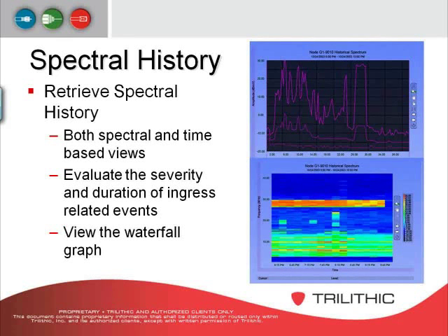And then on the very far right side, there are color codes that show amplitude. So if I know that my modem carriers are running at 30 meg, then I'm going to want to see what level is happening in that particular 30 megahertz band. If I see some orange in that 30 meg, I can look at my key on the side and it shows that that's at 20 dB.